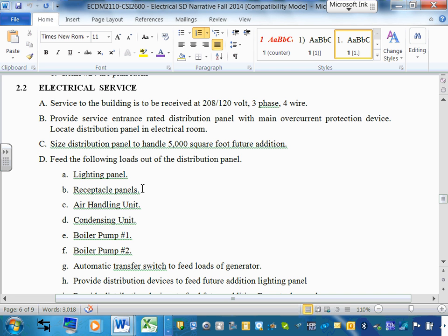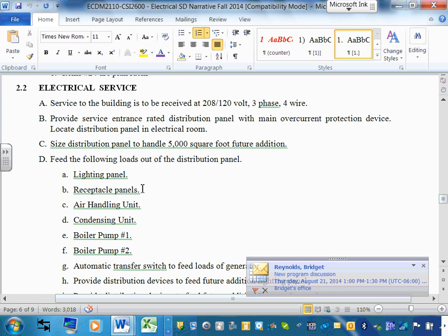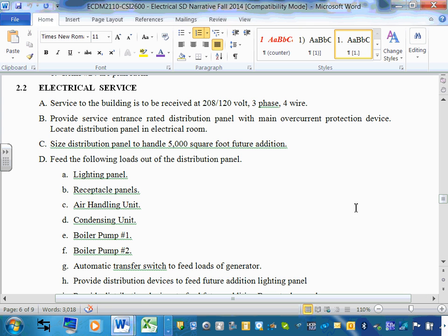If the load is an industrial building, 480/277. Airports, 480/277. These big data centers, 480/277. Office building, depending on the size. In this case, ours is what, 10 to 15,000 square feet. A good application for it will be 208/120. So important. As a project manager, we decided this one for you. Okay, so that's 4-wire delta, of course. And then a couple of things on how they want the distribution circuit. You need to accommodate for the 5,000 square foot future expansion.